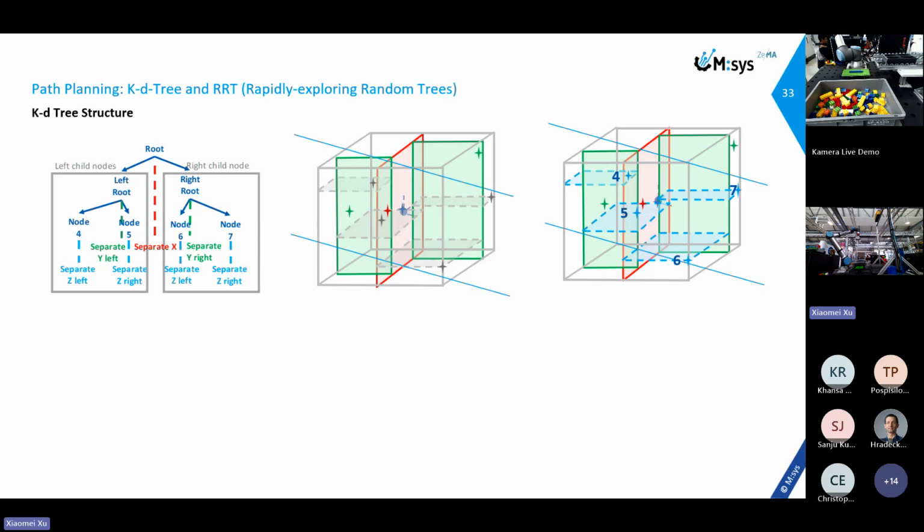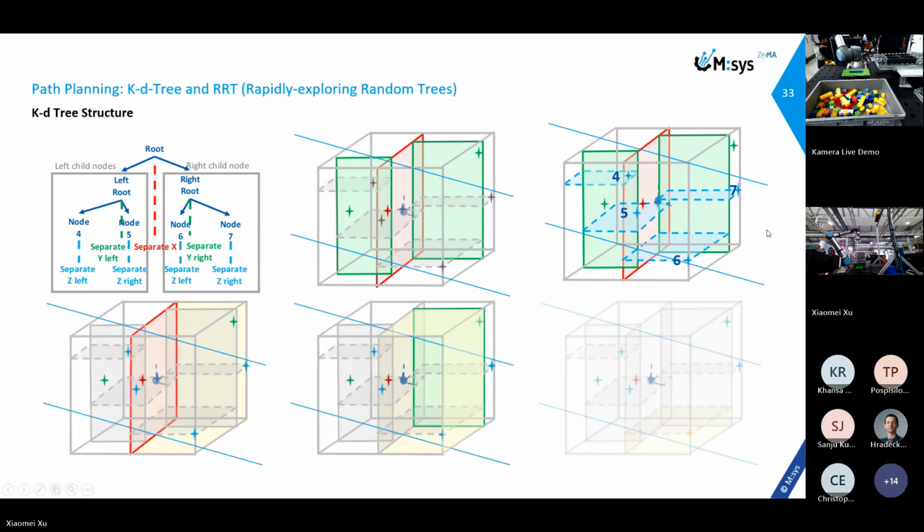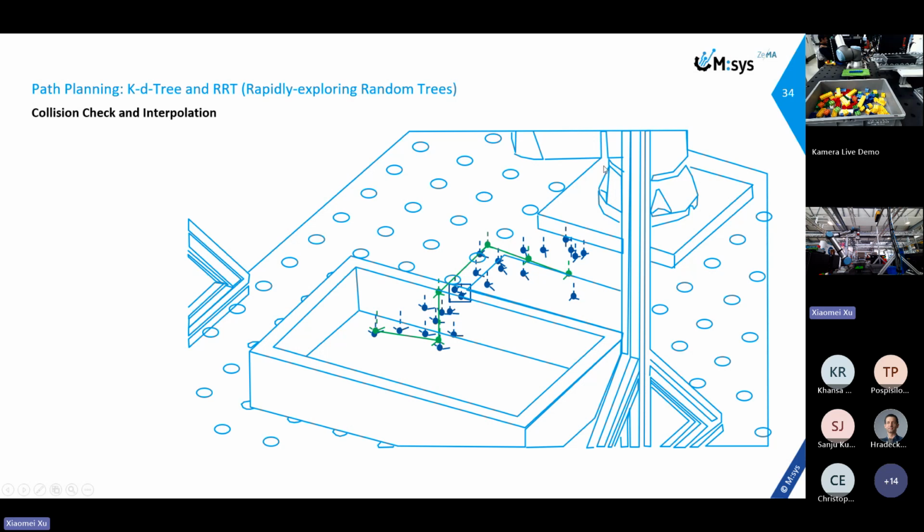Path planning in 3D space divides it into 8 subspaces along the X, Y, and Z axes. For faster collision-free planning in industrial reconfigurable environments, the 3D dimension balances computation time and complexity. The path planning is activated to define the start and end points within the workspace. The collision check treats each complex structure as a simplified base geometry shape to simplify the environment.